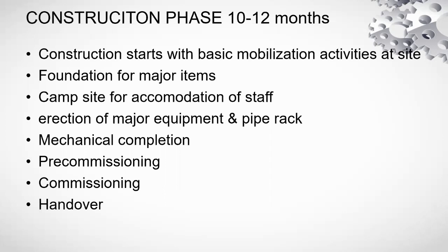If I have to put it in a nutshell, pre-commissioning is getting the plant ready for commissioning, and the commissioning phase is wherein you actually start the plant, you start taking in the feed, you start production, and you might produce something which is off spec, and then you have to reroute it through the plant and things like that.